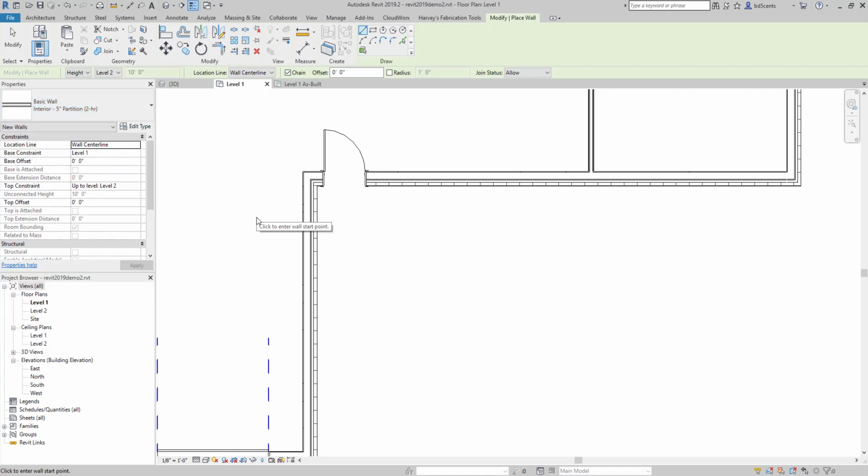In this lecture, you've learned you can copy a wall type, a roof type, a ceiling type, as well as a system family from one project to another. You can just cut, copy, and paste it. You could create a file and save it and put all your created walls in it, and you would copy and paste as needed from that walls file to your target drawing.